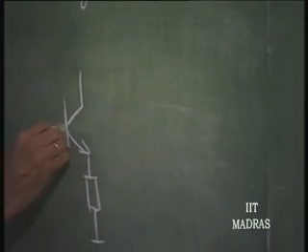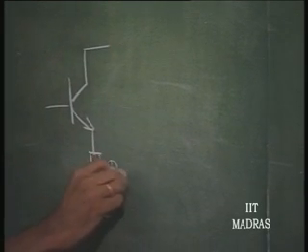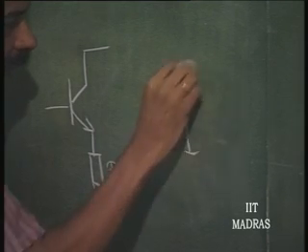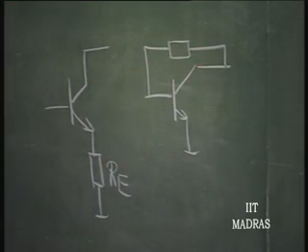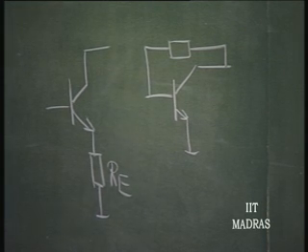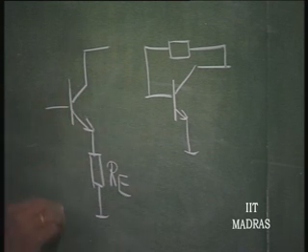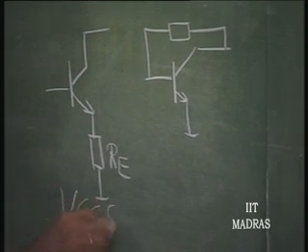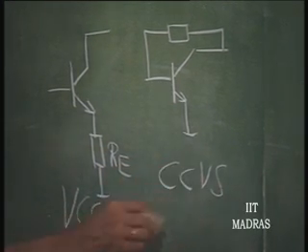So, such structures are the following. This we have earlier discussed, that is Z feedback and Y feedback. This we discussed in detail in negative feedback amplifier. These are wideband structures. This is a voltage controlled current source, and this is a current controlled voltage source.